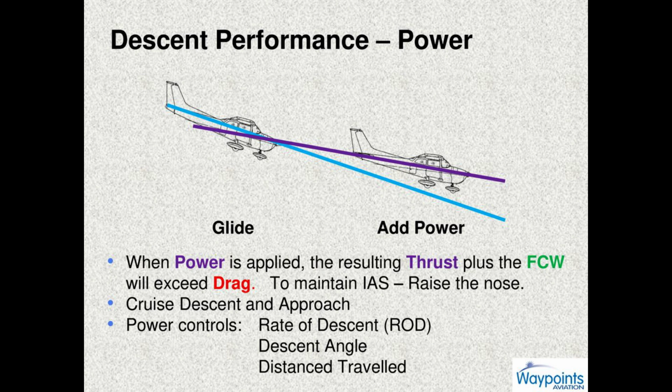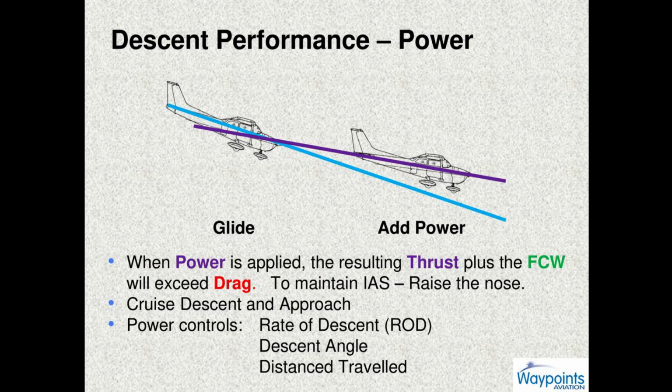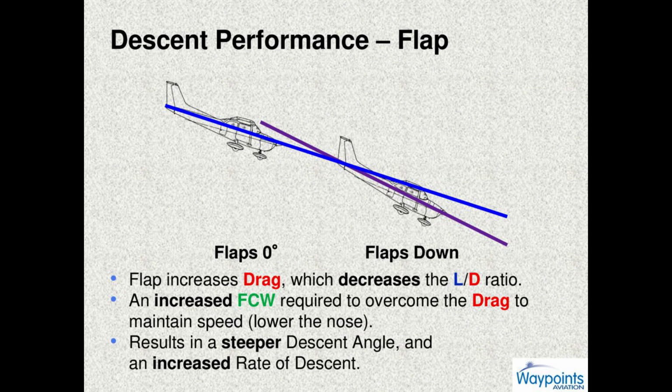Do not confuse a reduction in lift with the inability to generate sufficient lift to maintain level flight. The flight path is being manipulated with available thrust in reserve and with the elevator. To descend at the same airspeed as used in straight and level flight, the power must be reduced as the descent is entered. Entering the descent, the component of weight acting forward along the flight path increases as the angle of descent increases, and, conversely, when leveling off, the component of weight acting along the flight path decreases as the angle of descent decreases.